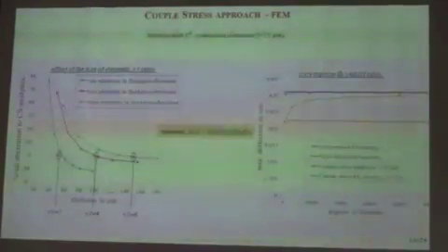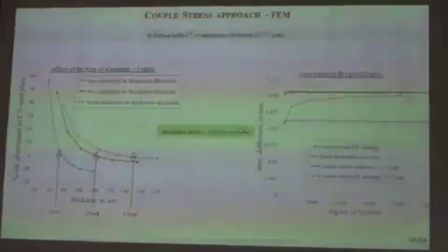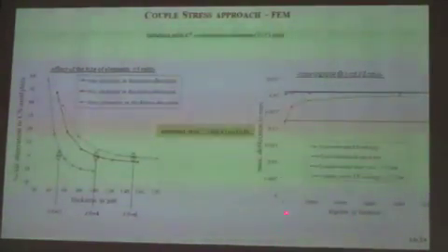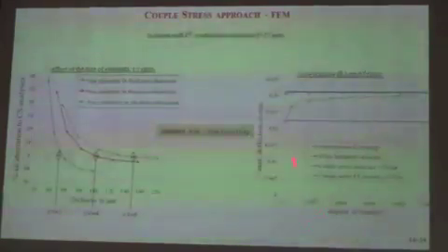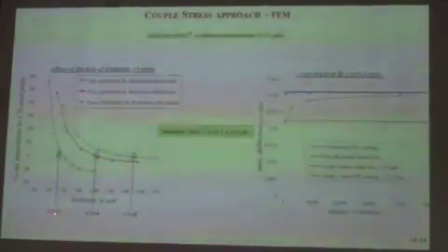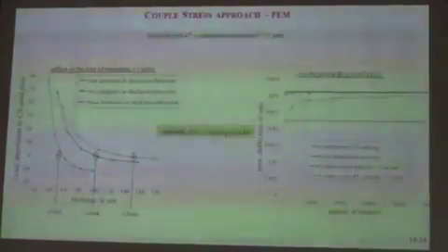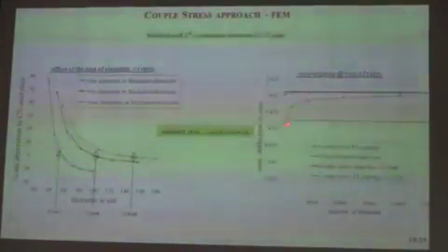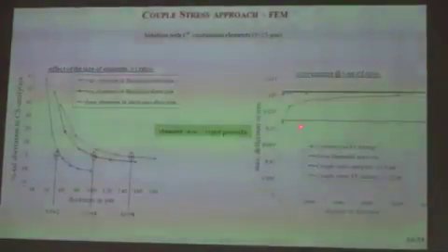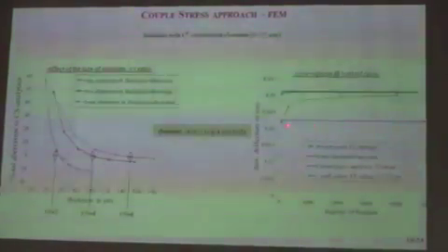If we now do the convergence, it's quite hard to understand, but if we increase the degrees of freedom stepwise, we start from such a good point, let's say, where the element size is identical to the material length scale parameter. We start at very good values for the coupled stress approach. That will be this line for bending.